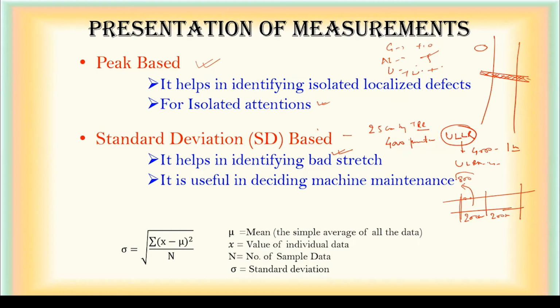It measures all 800 parameters and then calculates the standard deviation amongst these data. As you can appreciate, standard deviation is the difference from the mean value. So it gives basically the non-uniformity existing in the track within these 200 meters as compared to the mean value.